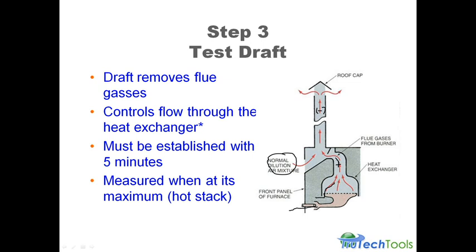So if we didn't have the draft hood that we have on here, find my felt tip here, yeah, there it is. All right, what we're looking at doing is we can either allow those flue gases to spill in the space, right, which is what they do. They go out the draft hood opening if the chimney was blocked. So we got blockage in here, we got a bird in here, whatever. This is all blocked off, right? No draft in the appliance. Well, the flue gases, which are naturally buoyant, are just going to spill out the front of the heat exchanger. They're going to spill out the front. And this is much safer than the flame trying to come out here and look for oxygen.